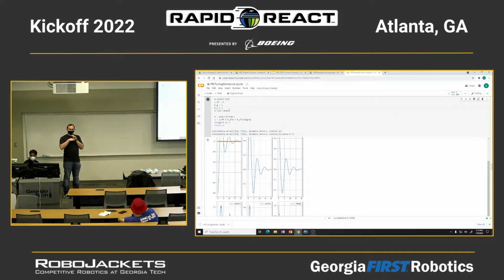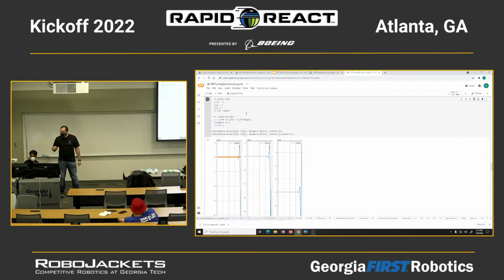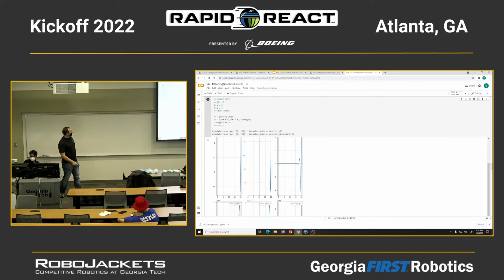Opposite? Same, right? Same. You're integrating the error and then multiplying it by a constant, versus just taking the current error and multiplying it by a constant. So at least initially, they'll move in the same direction. Once you cross the set point, I will probably tell you to keep going up because it's accumulated error, but P will tell you to go down. So what you'll see is much worse oscillations. Well, this will probably go crazy. So it just goes unstable.